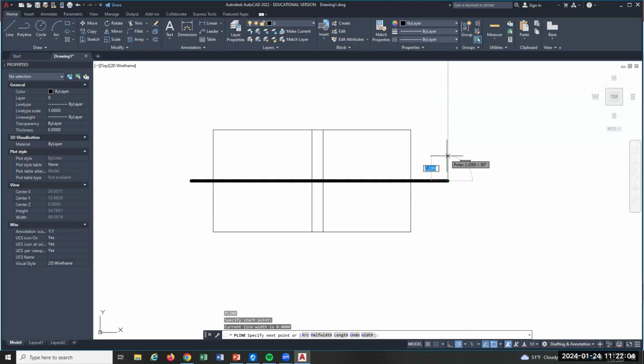Right? So, okay, I'm gonna add width. So I hit W for width, and it's gonna say, hey, what do you want for the starting width? And I'm gonna say, I don't know, 0.2, because I think I'm in US, right? It's weird that the line thickness is in metric, but it is. And then the ending width, I'll say 0.2, and I can see what I get. I'm like, oh, that's not bad. You know, this is maybe a little too thick. I don't know. I'll see what it looks like in layout in a second. So that's just thick lines.